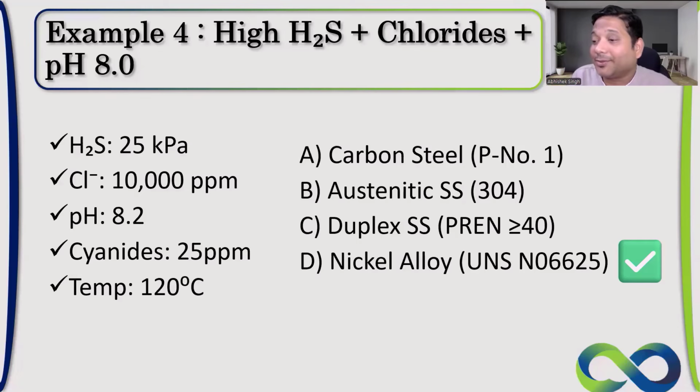Yeah. So definitely, Swapnil, if you find that the base material you cannot use, you can do cladding. That is where the cladding of Inconel comes into play. Okay. So you'll see heat exchangers getting cladding. So the reason is this, you want to use nickel alloy, but you don't want to increase the cost by changing the complete base material. So use clad. Okay. So normally, Inconel is used for cladding. You will never use it for the complete channel. Right. So definitely there are lots of requirements for clad overlay in that.